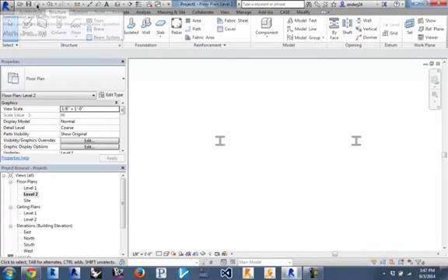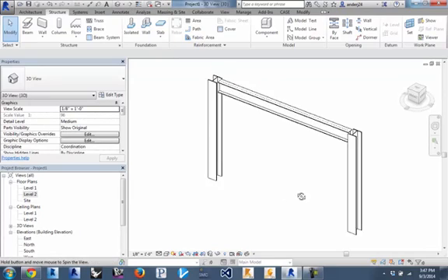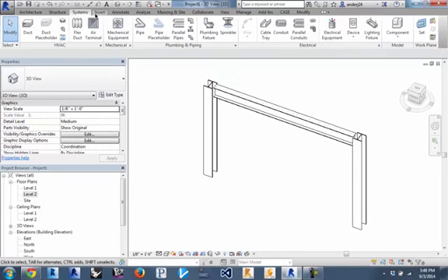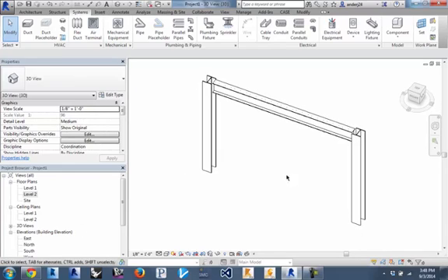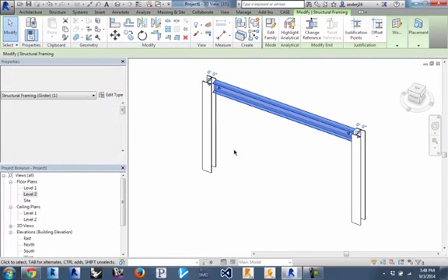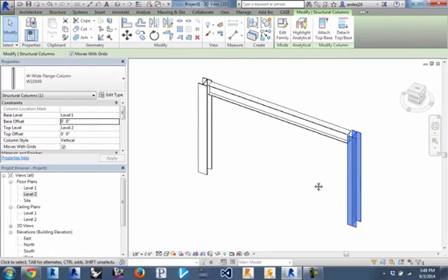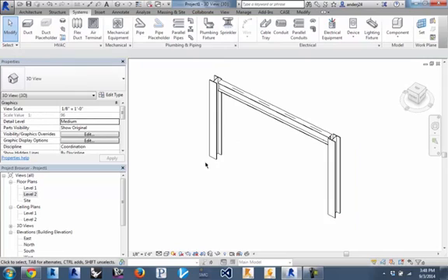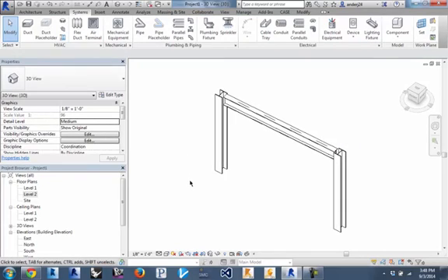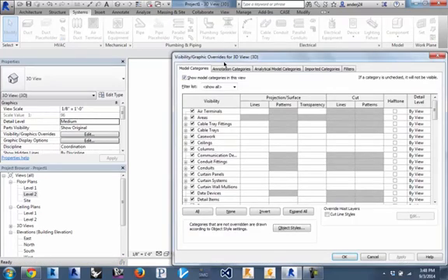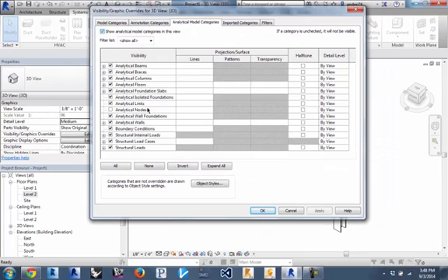How do we fix where you cannot see them again? What's going on? Oh, if you start out drawing, remember, draw it on the level above. And then once you get that, in the 3D view, go ahead and turn on all of the analytical information.